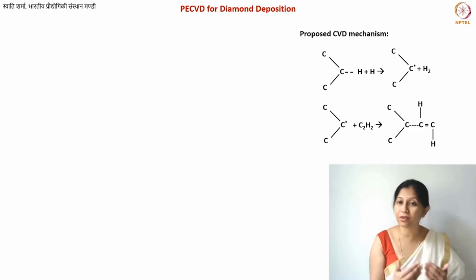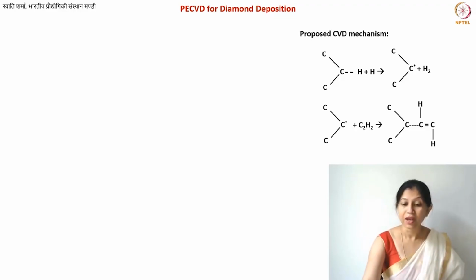So all the non-carbon atoms will then either cleave, or they will just stay in the system. That is why you also find some hydrogen present in your diamond-like films. But this is a mechanism of getting 4 carbons, or an sp3 type framework, to be formed. There are actually some other mechanisms that have been proposed, but this is something which has been experimentally verified multiple times, and that is why I have shown it here.